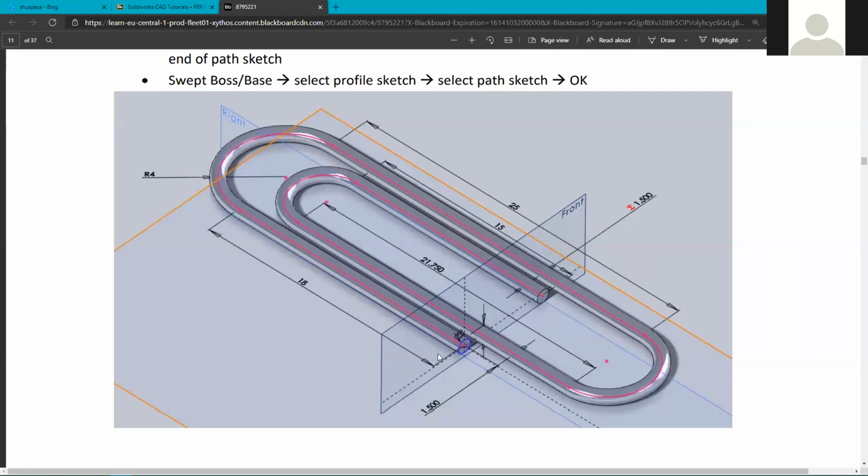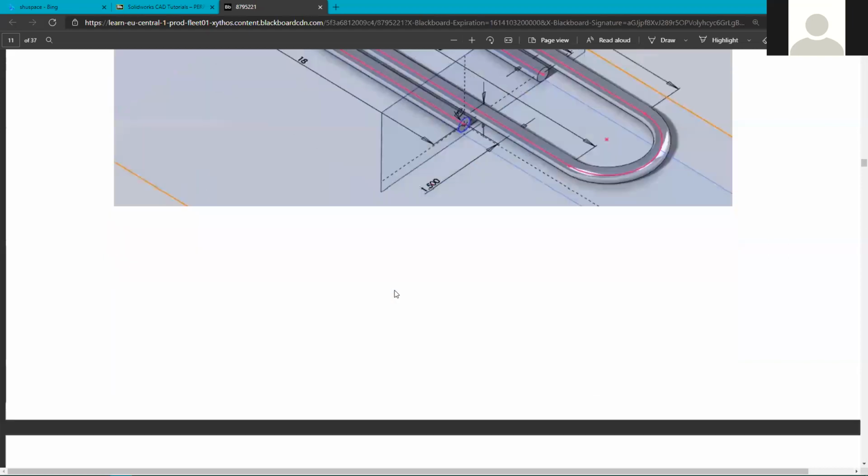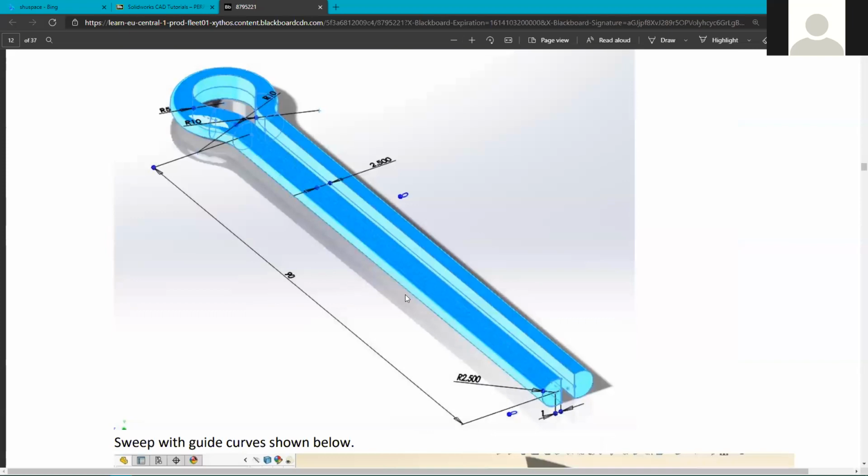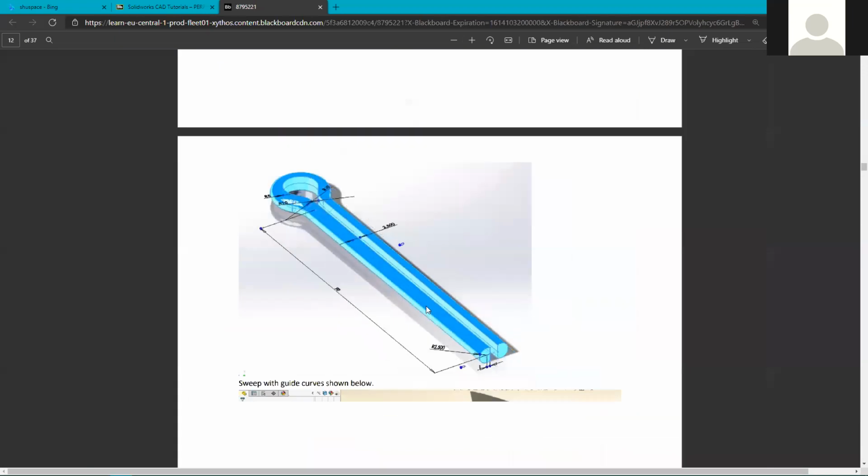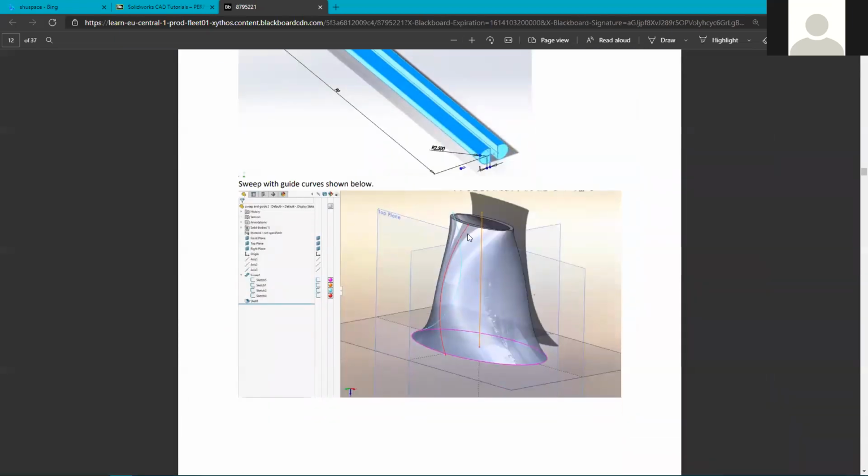In a way, it's similar to the extrude, but whereas with the extrude you can only send the shape off in a single direction that just happens to be a line, in this we can direct it round corners or in any other shape that we want. So we'll have a go at that one. Then we'll practice what we've done with this split pin shape as well. And then we'll talk about some of the more advanced options within sweep.